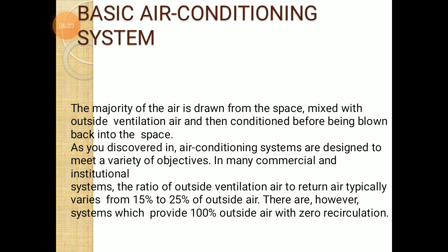In many commercial and institutional systems, the ratio of outside ventilation air to return air typically varies from 15% to 25% of outside air. There are some systems which provide 100% outside air with zero recirculation.